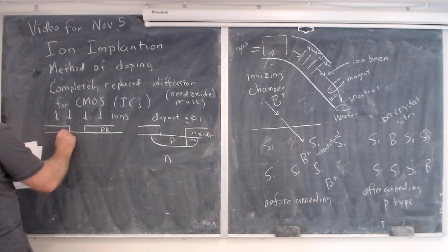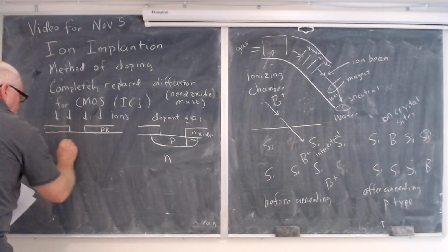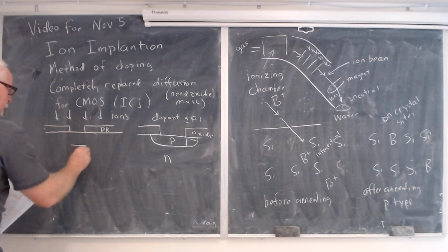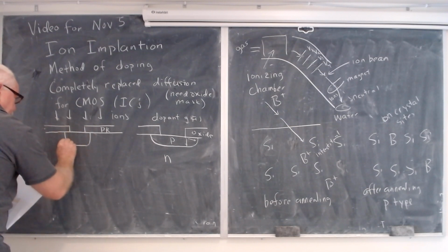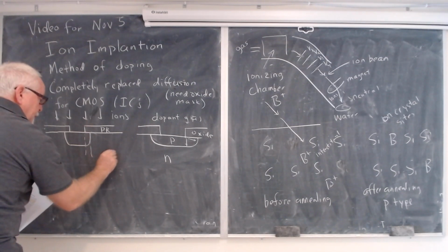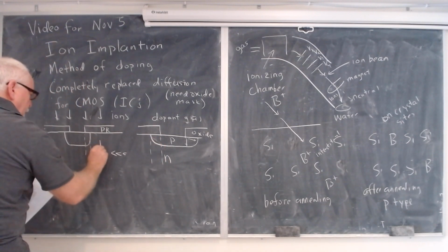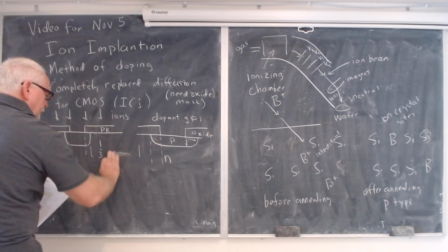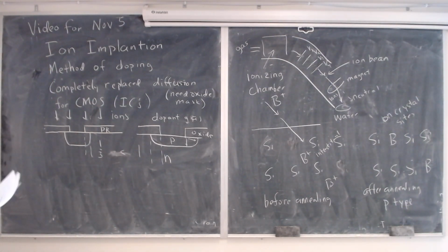step, the rule of thumb, they had it here, is 1/3. Meaning if it goes down this far, the lateral spread is about 1/3. It's 1/3 compared to 1. 1/3 is less than 1. So you get much more control over the lateral position of your dopant atoms, which means if you're fabricating a device, you can have that much more precision, of course.